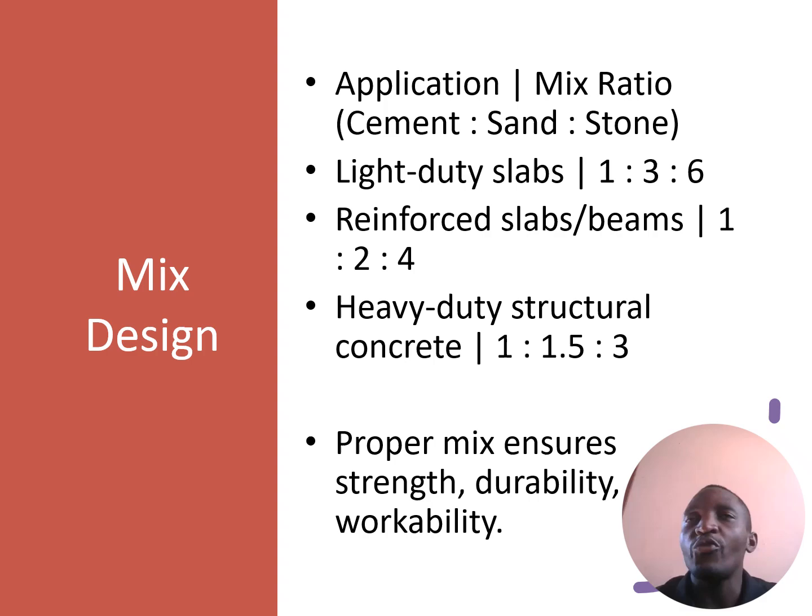When you mix for light duty slabs, you're going to use 1 cement, 3 wheelbarrow of sand, and 6 wheelbarrow of stones. The ratio is 1 to 3 to 6. You must make sure you follow the ratio for light duty slabs.